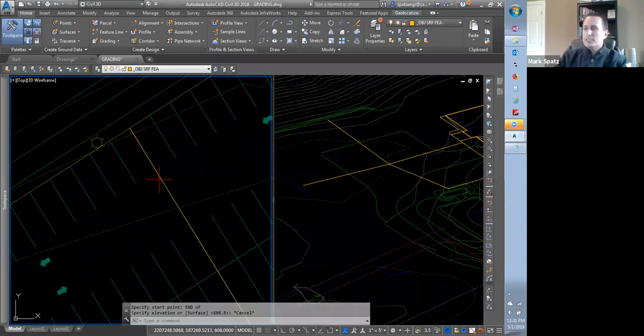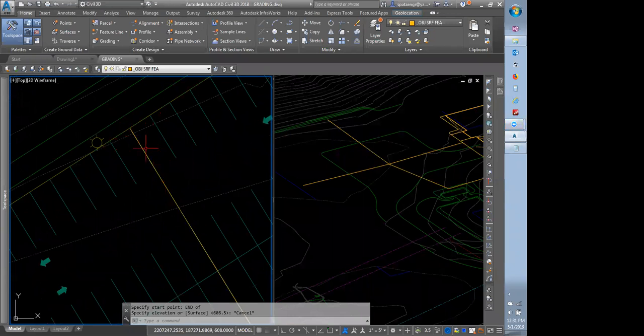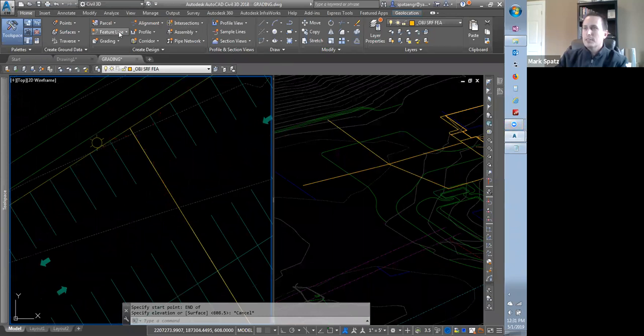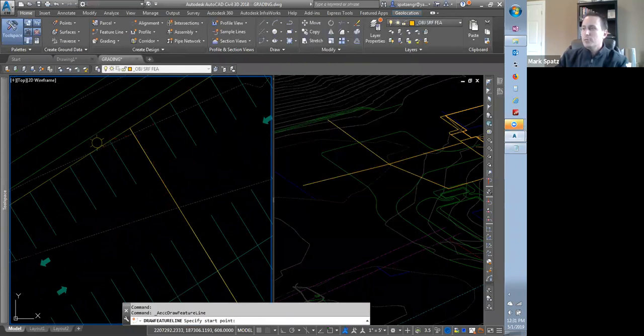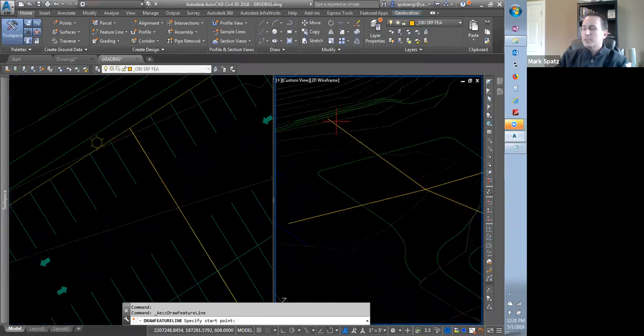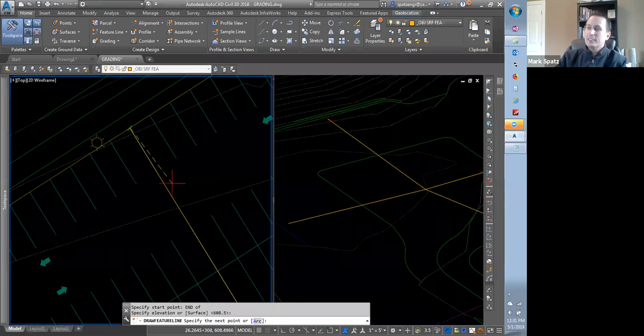Whenever I have that scenario, where it's right over this striping, I always want to try to snap using the 3D view. I don't want to risk it; you can see it in the prompts, it would say 0, but you're surely going to get the endpoint at elevation if you pick this. So apparently that's 608.5, hit enter.